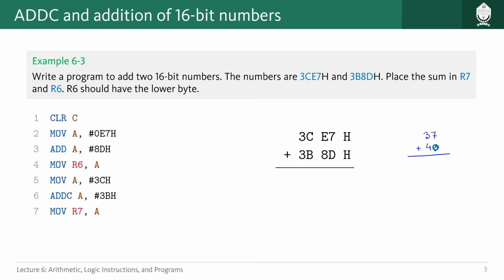If I add these two values, 7 plus 9 is equal to 16, but we never write 16 directly here. What we do, because this is based on arithmetic, from this 16 we keep 10 aside and just write 6 here, and that 10 becomes 1 for the next stage, right? Here we use that as carry basically, and then we add these two things, it will be 8, right? In this way we do calculation for decimal addition. So whenever we are talking about hexadecimal, the concept is similar, but here the base is 16, so we have to think in terms of 16.